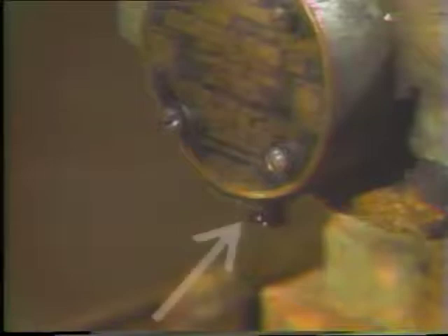Wipe off the grease fitting and make sure the opening is clear. Then, attach the gun to the fitting on the housing. Applying grease while the bearing is in motion helps to distribute the grease more evenly. Grease should be added slowly until it begins to come out of the drain. The machine should be run for several minutes afterwards to make certain that all excess grease has been forced out of the drain. Then, wipe off any excess grease and replace the plug.